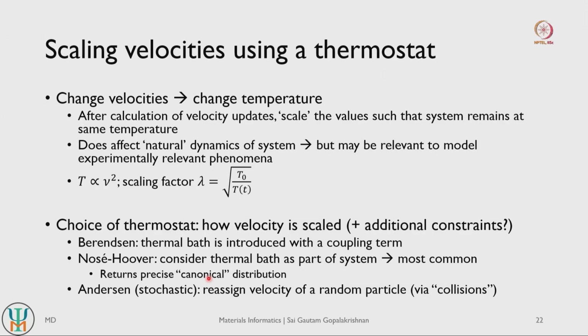So given a temperature, you can get a distribution of velocities that represents a true system, and Nosé-Hoover is usually good at getting the true representation of velocities for a given temperature in a given system. So almost always Nosé-Hoover is a good place to start when it comes to thermostats. So if you are new to molecular dynamics and interested in doing constant temperature simulations, start with Nosé-Hoover.